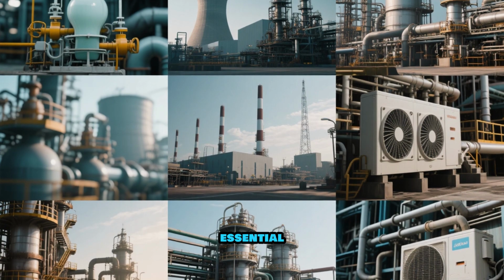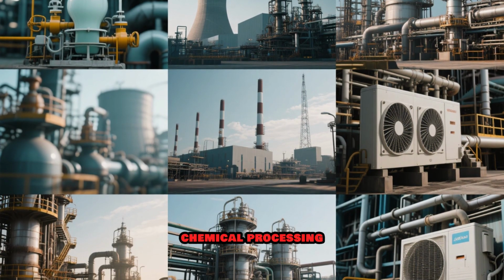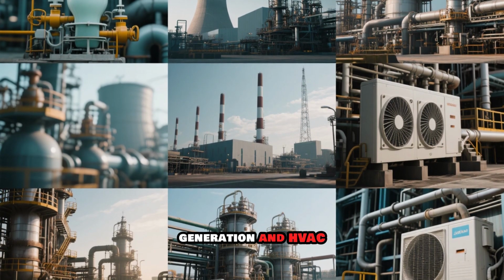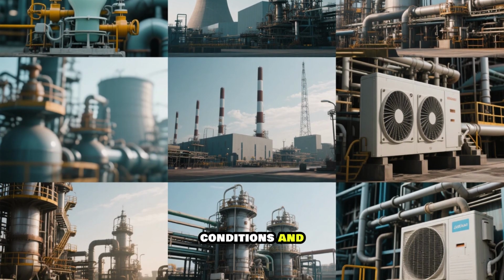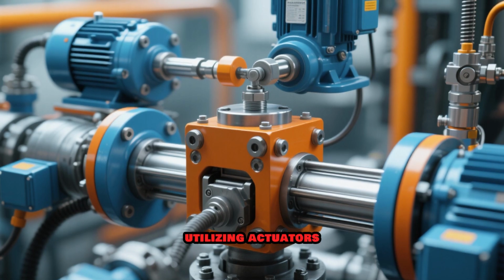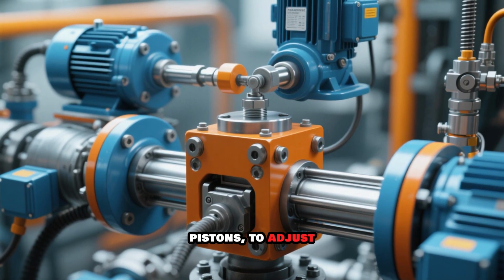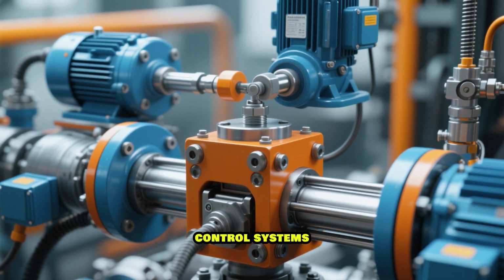Control valves are essential components in various industrial processes, such as chemical processing, oil and gas refining, power generation, and HVAC systems to maintain desired process conditions and product quality. They achieve this precise fluid regulation by utilizing actuators, which are generally electric motors or pneumatic pistons, to adjust the valve's position according to signals from control systems.